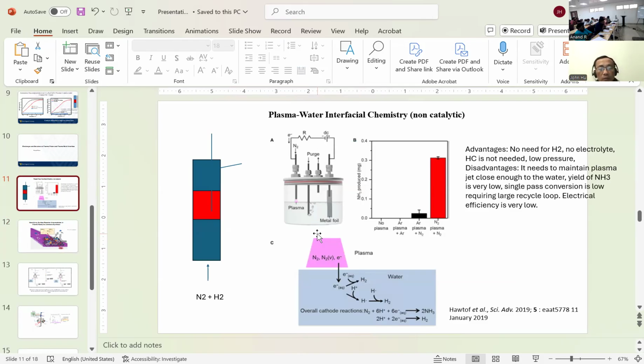But now, when you have it here, oxygen will be the problem. I think that's the reason they use the purge, to make sure that the entire chamber is oxygen free. They have to purge very fast, because oxygen is constantly produced from water. The moment it forms, they have to purge it out. So good question. Okay.